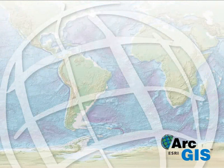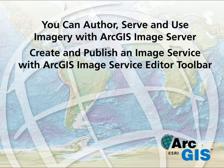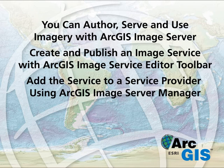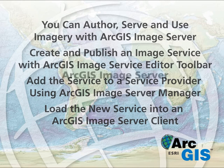In this demonstration, you have seen how to author, serve, and use your imagery with ArcGIS Image Server. In particular, you have seen how to use the ArcGIS Image Service Editor toolbar to create and publish an image service, how to use the ArcGIS Image Server Manager to add that service to a service provider, and finally, how to load this new service into the ArcGIS Image Server client for use in ArcMap.